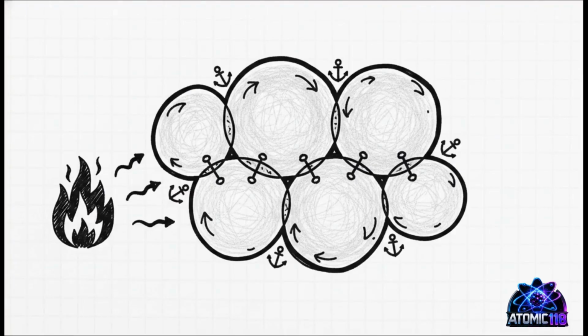Let's talk about a really cool phenomenon called grain boundary pinning. This is how vanadium physically forces the steel to maintain its fine structure under heat. Think of these fine vanadium particles as microscopic anchors. They physically lock the expanding austenite grains in place when the steel gets heated up, totally resisting structural degradation. Austenite is basically the high-temperature phase of steel where it gets moldable.